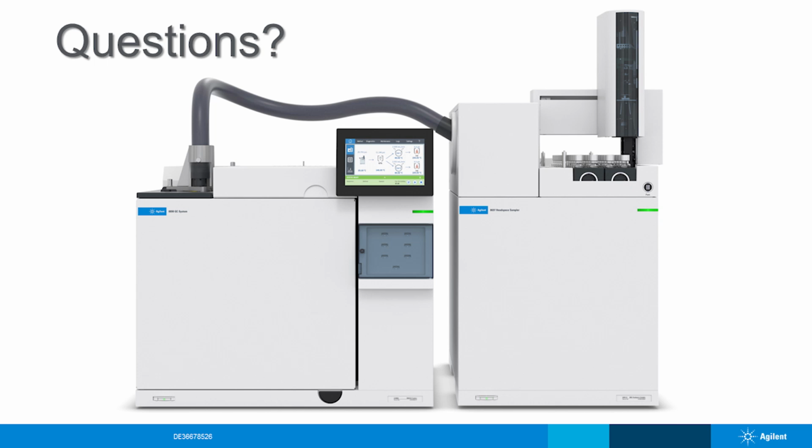If you're changing the volume of the sample, you're also changing the amount of vapor space that can hold the partial pressures of your analytes, which is the part that we're actually analyzing. So that's called the phase ratio, and that gets into the theory of headspace sampling. So that needs to be consistent.